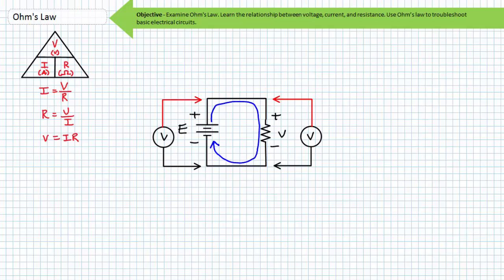This is again probably self-evident with just one element in our circuit, because there are only 2 nodes in this circuit, and voltage is a 2-point measurement. The 2 voltmeters are in effect reading the same voltages because they are reading voltage at the same 2 nodes. What goes up must come down. Keeping track of the polarity of voltage rises and drops for circuits with multiple elements and even multiple sources will become exceedingly important in the future.